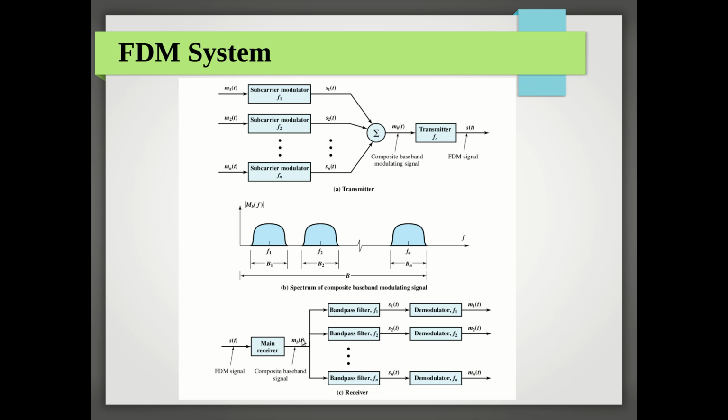The total signal contains different channels combined together, and each one is centered on a particular frequency. To get one part alone, we can use a band pass filter centered on that frequency. A typical band pass filter filters the total information so that only the spectrum of information centered on the frequency f1 comes out as the output of this particular filter. So this band pass filter passes the range of frequency centered on f1 as output, and that limit can also be fixed, as these band pass filters are designed.